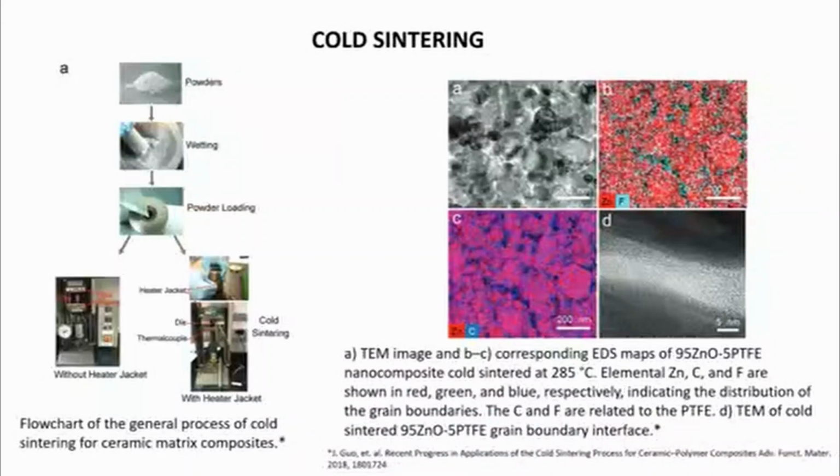The general process of cold sintering for ceramic matrix composites includes the mixing of ceramic powders with fillers, powder wetting, and sintering. Traditional mixing methods such as ball milling and mechanical stirring can be used to homogeneously disperse fillers onto ceramic. Cold sintering requires a transient liquid-assisted sintering under certain pressure, which then shows a similar densification process to that of liquid phase sintering, and thus uniform wetting is critical in the cold sintering process. The selection of the solvent phase requires suitably fast kinetics of the congruent dissolution of the surface ions of the ceramic phase.